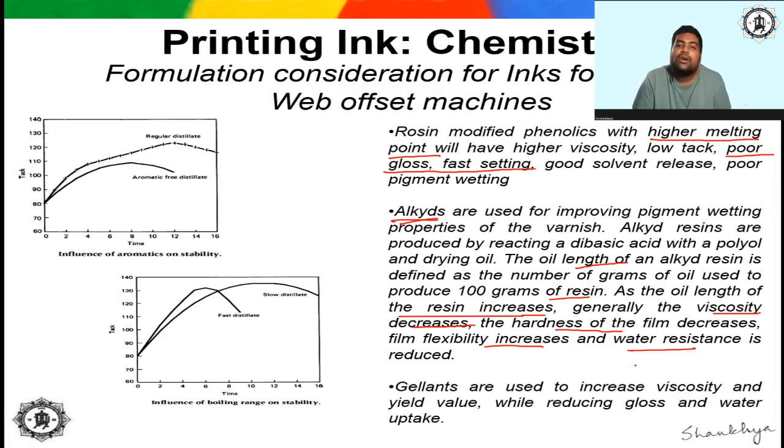That is a water-in-ink emulsion, right? That means the main dispersion medium is ink, with a very small amount of water within it. But if the ability of the ink to take up water is increased, then that emulsion will be destabilized, the balance of ink and water will get destabilized, and scumming will occur. This is another problem that can occur.